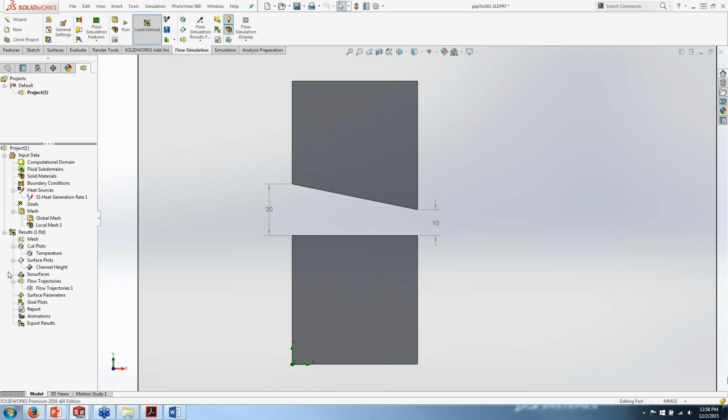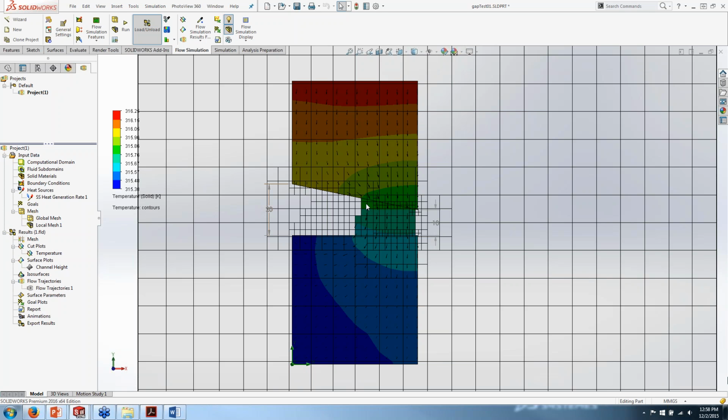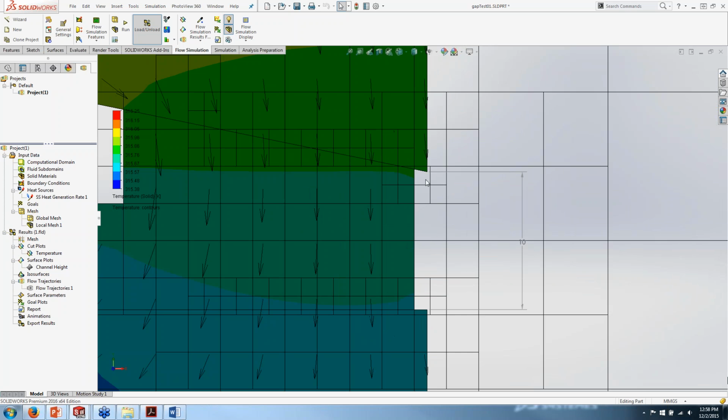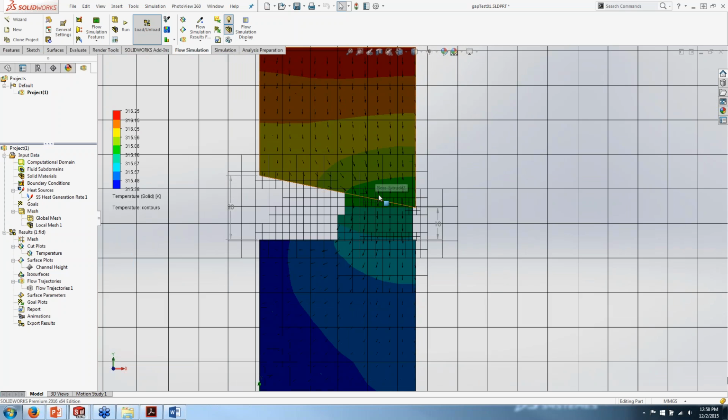I put a heat transfer on this so you can kind of see the temperature across here, and you can see kind of how it closes that region. Looks very interesting. Okay, you can see these cells, the ones that are closed are the ones that are colored in. Okay, so it's treating that region as solid. So notice, interestingly, it didn't close the very edge here, though. Okay, so it only seems to be closing the cells that are sort of completely within the gap region. Okay, so it allows for heat transfer across that region, which may or may not be desirable.